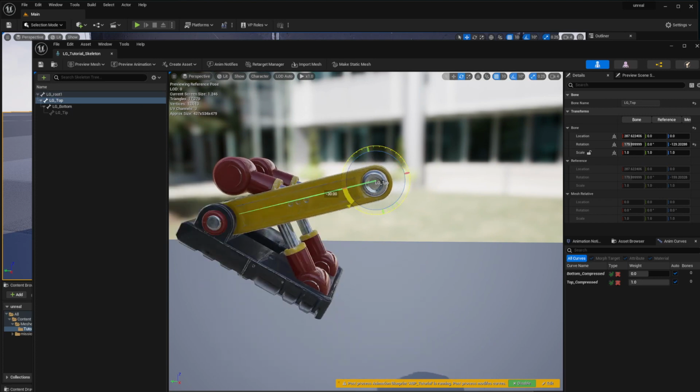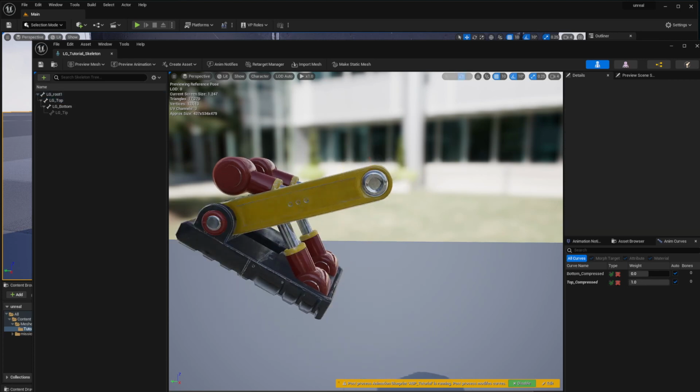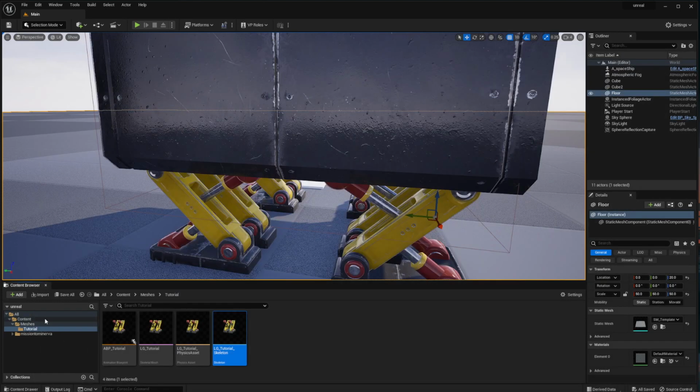When we have our rotation at 30-30, we have the minimum distance that we can extend our landing gear, and at 0-0 we have the maximum extended position for our landing gear. But at 15 we are not at the middle of this distance. The distance value is not directly changing with the same rate as the angles that we want to rotate our landing gears to, and that's why we created this curve variable earlier.